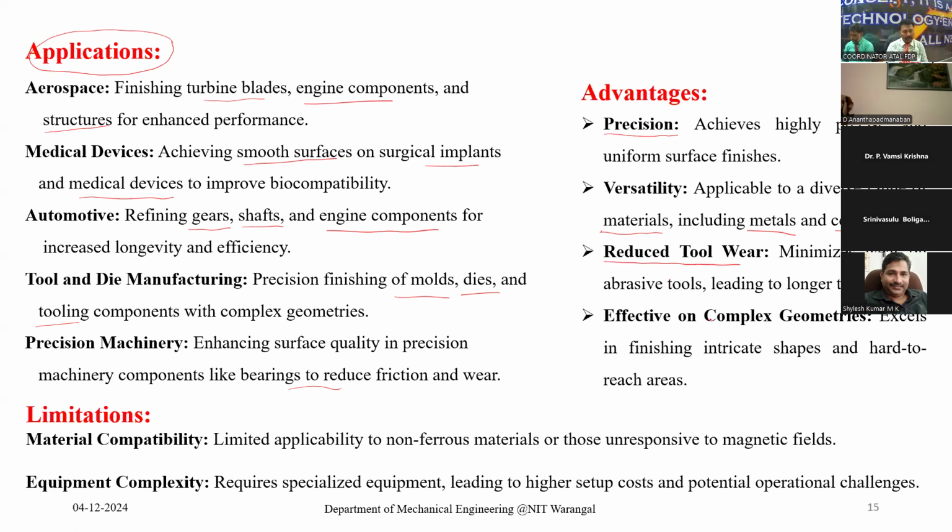After a long time only we have to replace this one, and then it is very effective on complex geometries. Like we use a brush to polish our shoes, or we use a brush to clean our teeth. It is flexible and it goes into intricate shapes, and it reaches hard to reach areas which are not possible with grinding operation. But there are certain limitations in this process.